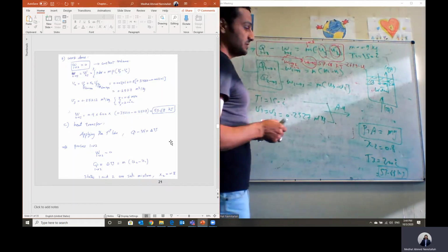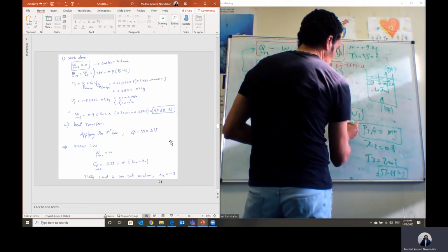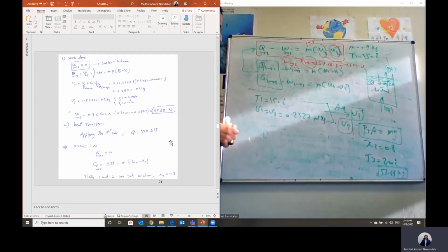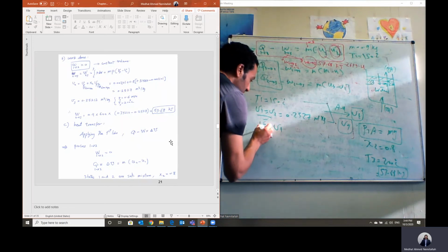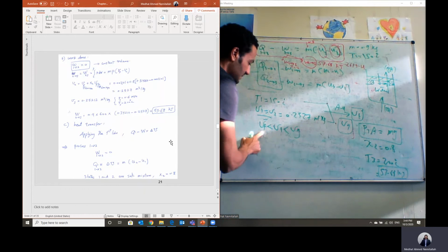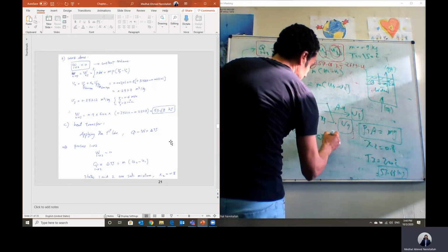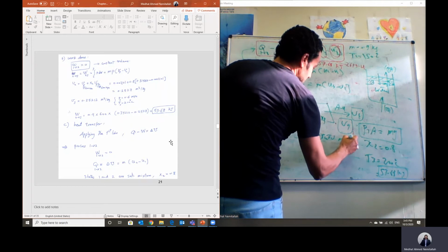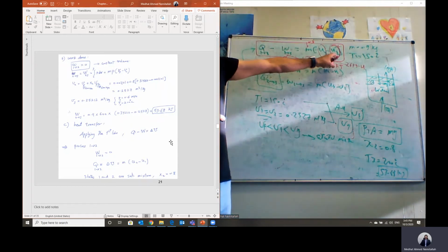From the table I will get V fluid, and also the value of specific volume V gas. Comparing with this specific volume, you will find that V1 is greater than V fluid and less than V gas. So the state is a saturated mixture.